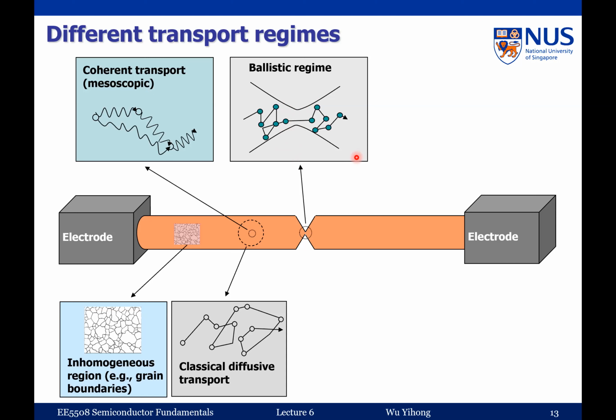The contact resistance for a single channel is actually a fixed value. Again, it's called quantum resistance. So that's why even in ballistic transport, if you measure it, you do not get a zero resistance, because you still measure the contact.